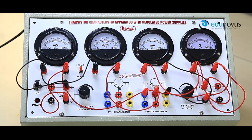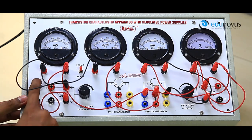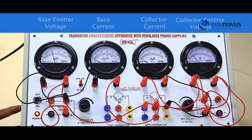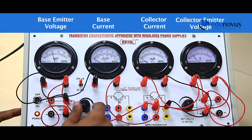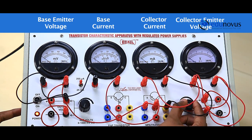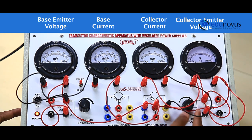Let's switch on the power supply and let's set the base emitter voltage and collector emitter voltage to 0. While keeping the value of the collector emitter voltage constant, we will now note down the value of base current for different values of base emitter voltage.